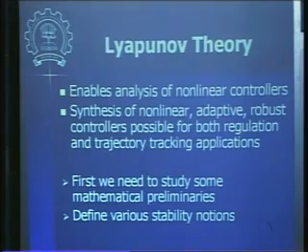Why should we study Lyapunov theory? It enables the analysis of any nonlinear system. And you know from robot dynamic equations that they are highly nonlinear in nature. They will have sin theta, cosine theta terms or square terms of the velocities.